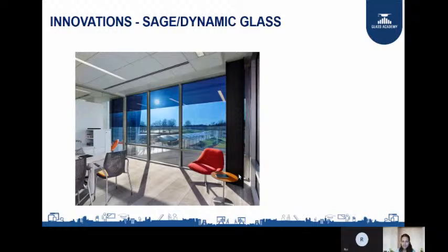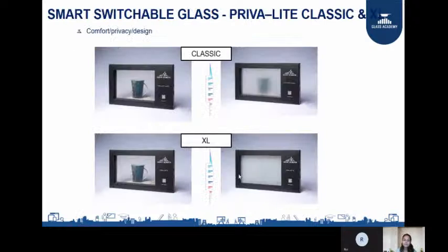If you can see here, if my tempered glass breaks, it will break into very small pieces, like mentioned here in the slide. But if my glass is not toughened, if my glass is not processed, if it is normal annealed glass, it will break into very large pieces, which you can see here on the right side. So this is how toughened glass is manufactured. You do the processing on the raw glass.